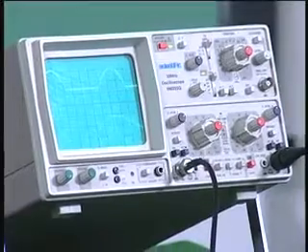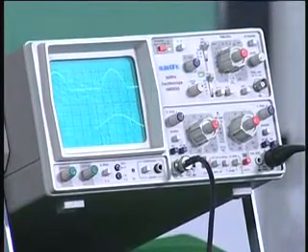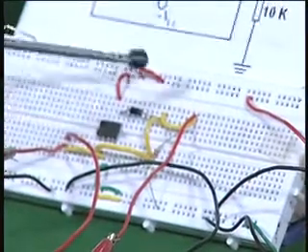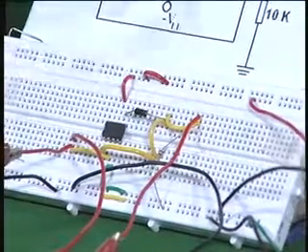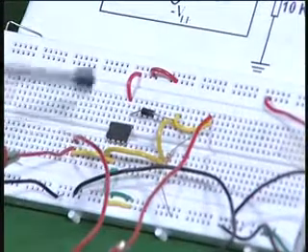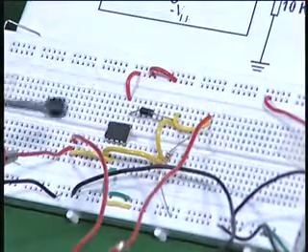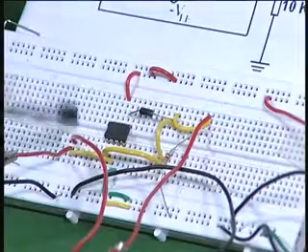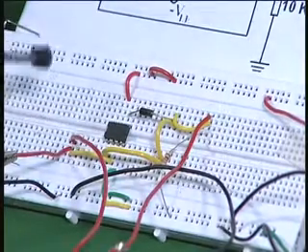So it is a very simple circuit. Again you can see I have used only one op amp and one diode in the feedback loop, a very simple circuit which is able to perform rectification even for very low signals. How do you know it is doing it for very low signals?